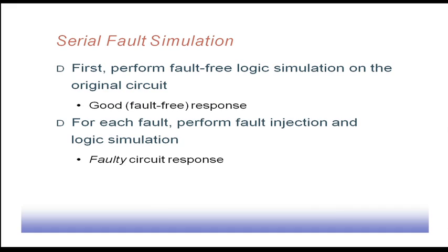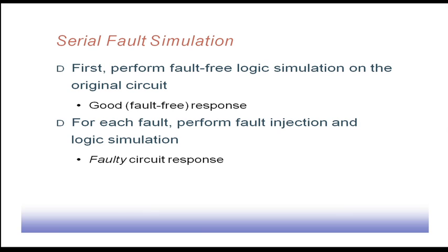Then for every fault, we perform fault injection and logic simulation. Performing fault injection means we modify the circuit description as if that particular fault has been inserted into the circuit, and then we simulate the circuit again. So, in the presence of that particular fault, what is going to happen? That is the logic simulation after doing the fault injection.